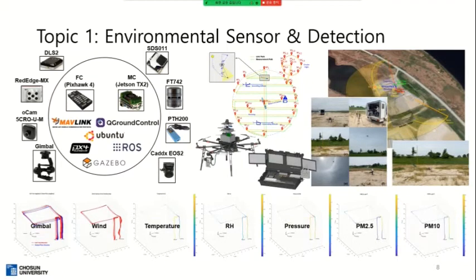In this development, the contribution is that we can control the direction of the multispectral camera and RGB camera by using the gimbal. To do that, we tried a PWM signal, both PWM signal and MAVLink signal, and also UART serial communications. But we ended up using PWM, the most basic signal process, because of its robustness.